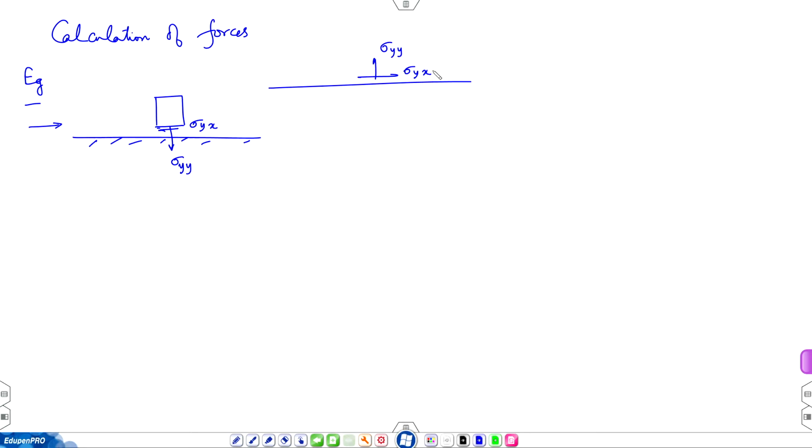Now, let us write the force acting on the surface in the x direction. Now, we are doing a calculation of force on the surface. You remember that the control volume analysis was for the fluid medium, and then we got forces acting on the fluid medium, and then we transferred that force information onto the solid surface. We are doing the same force calculation now with respect to locally available flow properties. So, this stress tensor was for the fluid element, and now we are transferring the data sigma y y, sigma y x onto the surface.